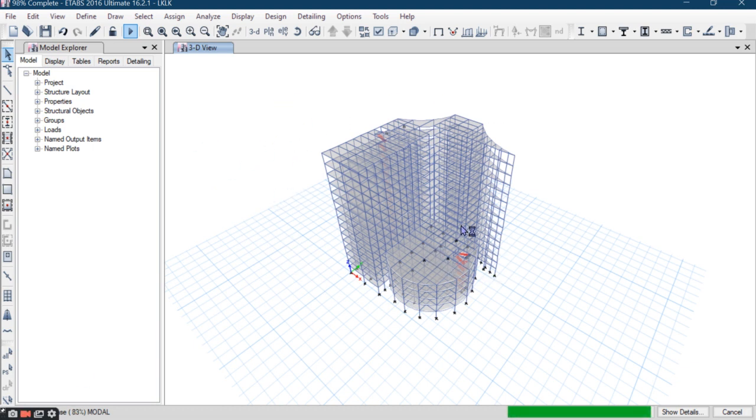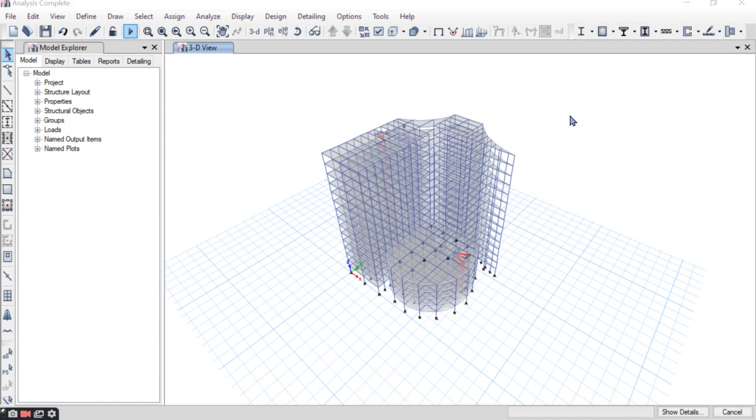And for the bending moment, you can use these formulas. For the bending moment, we check WL square by 8 and the shear by WL by 2. This bending moment is for the continuous beam. For the slab also we can check span by 250. So it is taking time. This project is taking time.